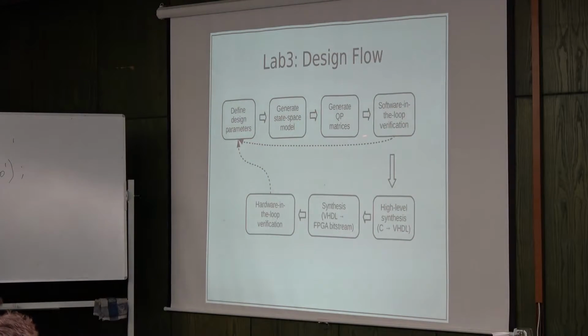Once you do this, the next step is, you have your C code at this stage, and you give this C code to a high-level synthesis tool, to Vivado HLS, that will convert your C code into VHDL.